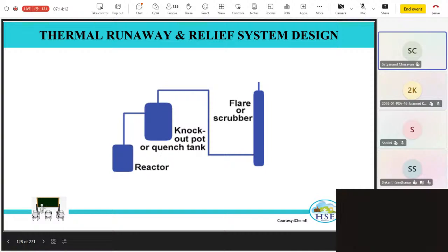The heart of process safety studies is reaction calorimetry studies. So use reaction calorimetry appropriately and generate wonderful data, because you can use that information not only to design a safe process, but also an optimal, cost efficient and profitable process as well.